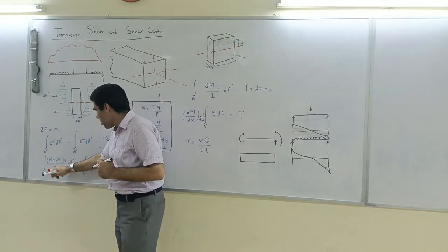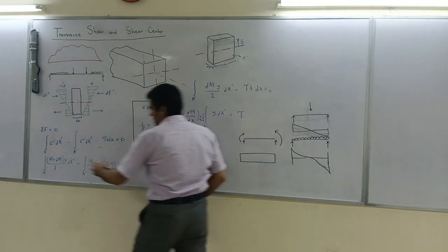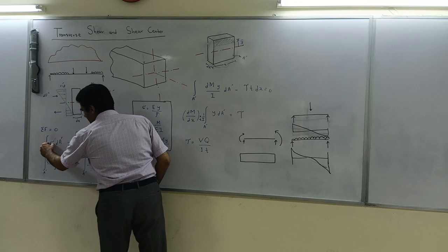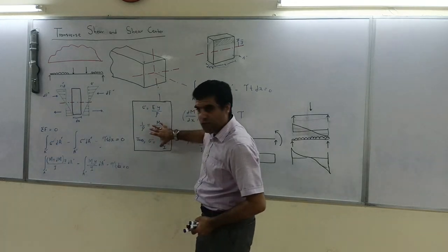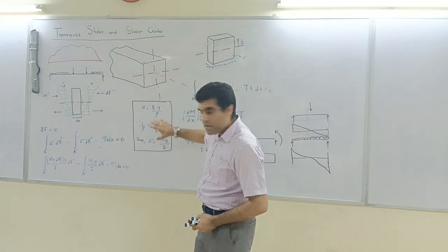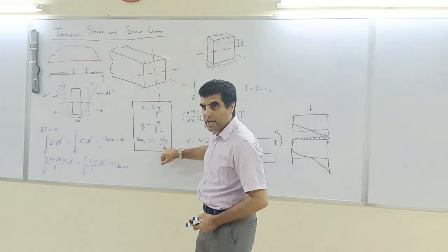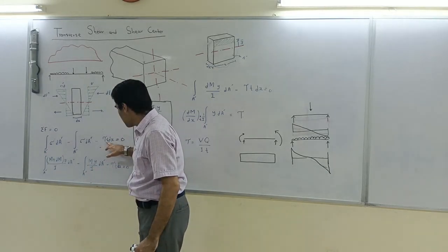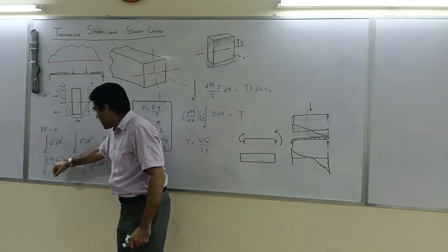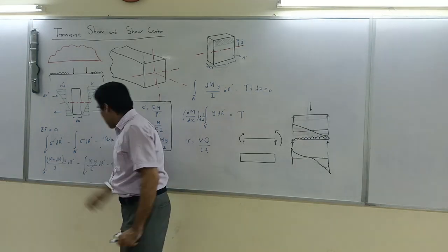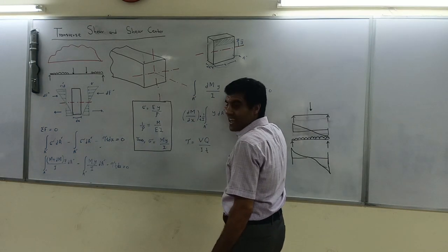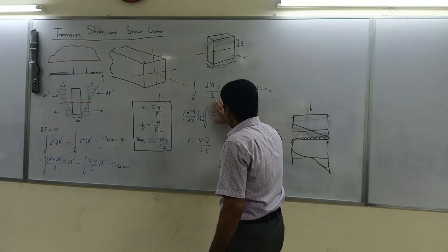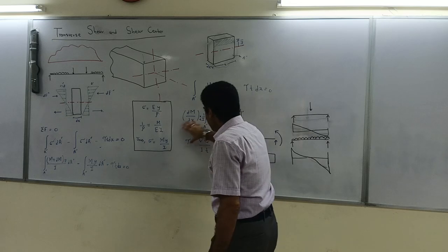What we have done is put in the value of stress dash, which for your convenience I have written over here. From a previous class we worked it out as M y over I. So this one minus this one will come as it is, tau dx. M and M cancel out, and we end up with M y over I dA prime, minus tau t dx. This one will go on the other side, tau in the end.